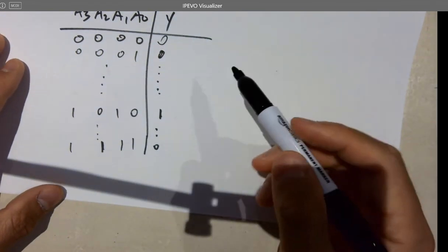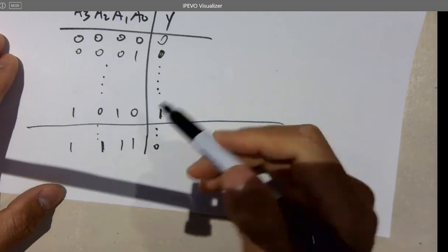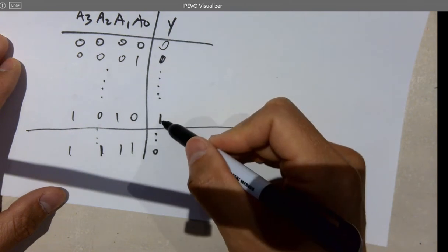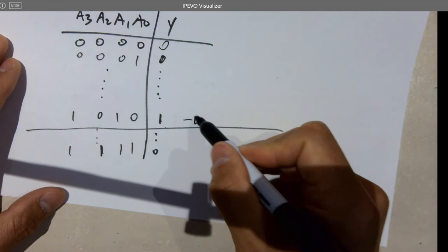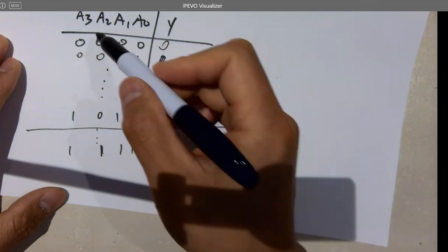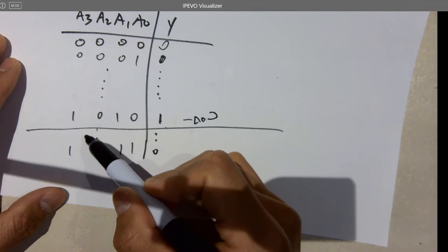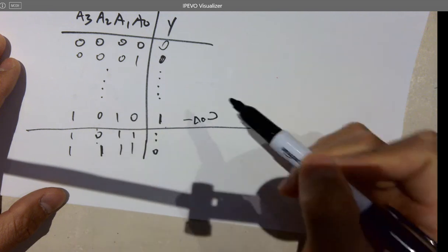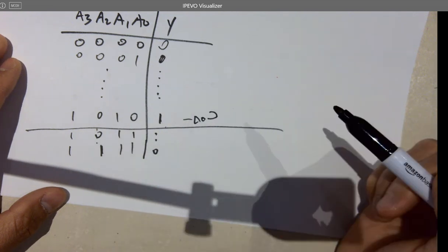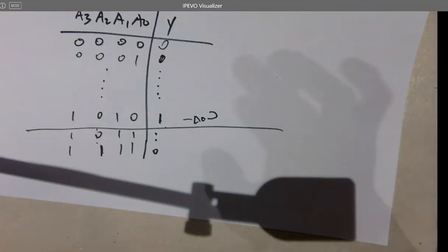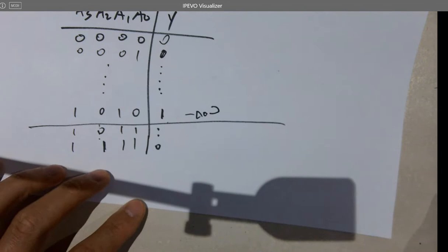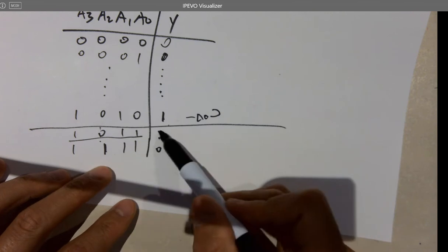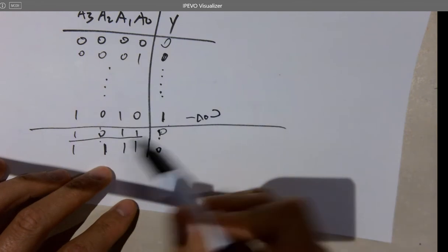So you are thinking, you're just counting to 10, and it's going to set the output. So it's been zeros until 10, so it's going to set. And then you want to invert this signal and reset the counter. So it's actually not going to count after 10. All these like 1, 0, 1, 1, this just won't even happen, which is totally okay, but you still don't want to give any ones. Just in case there's some errors in the circuit, and this kind of combination appears as an input and it's giving you a 1. You just don't want that to happen, right? Just all zeros with all the other inputs.